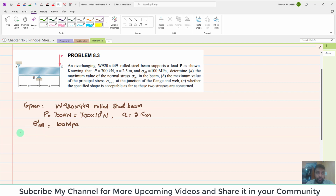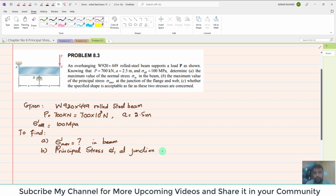So what you have to do in part A is find the maximum stress in the beam, or normal stress. In part B, you have to find the principal stresses, that is sigma 1, at the junction of web and flange.